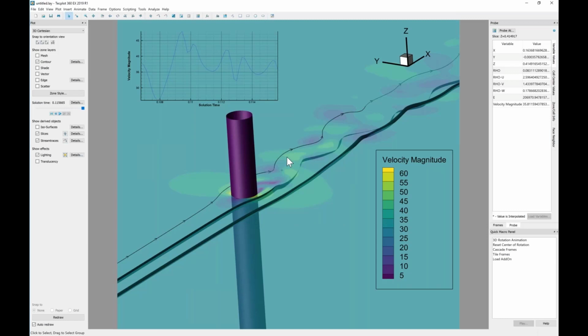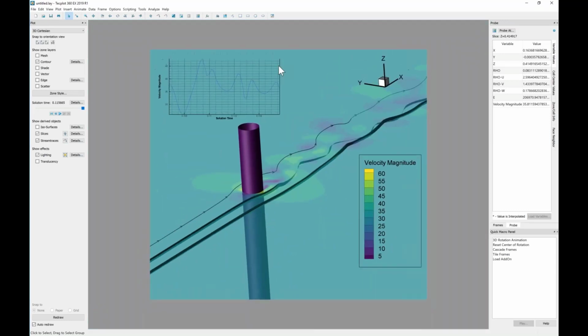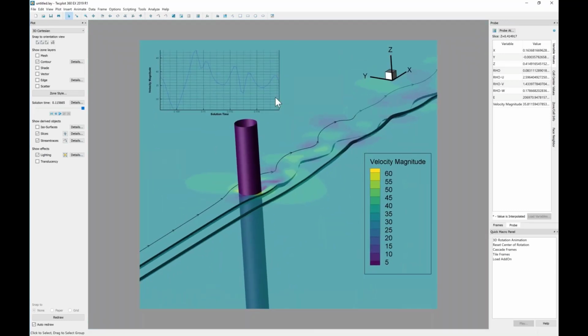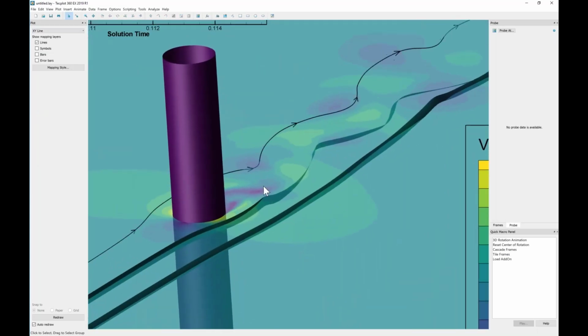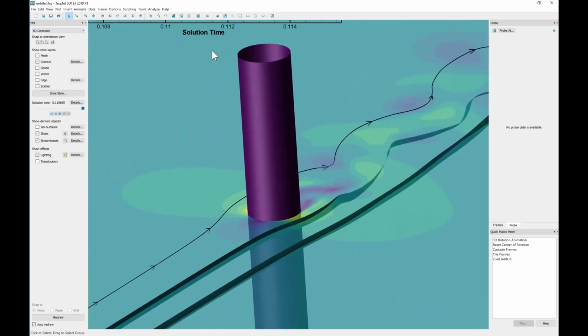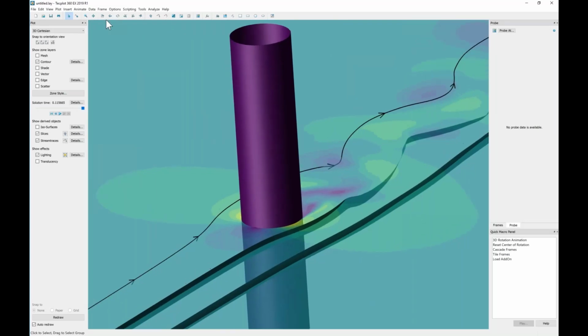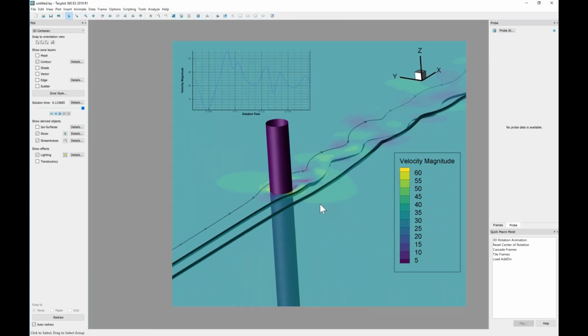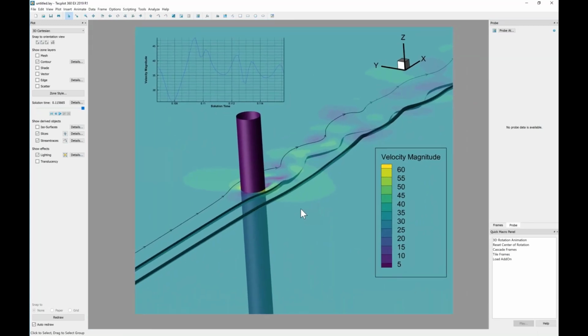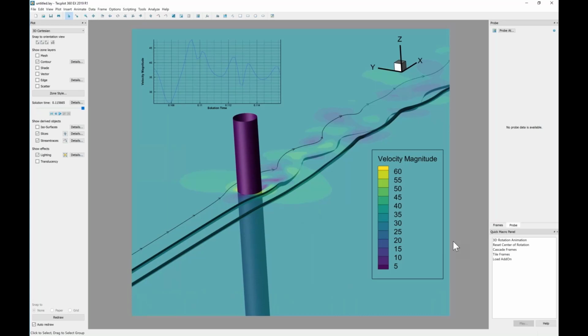So I guess if I wanted to crop, I could do what we call a paper zoom. So I'm holding down the shift key and I'm zooming in, and so I'm kind of bringing everything closer. And so a work area export is going to crop or export everything in this work area region. I don't know if that exactly gets you what you want, but that's an option that you could use.